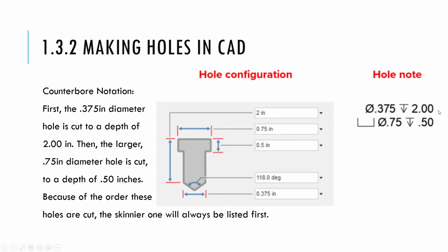You'll notice there's no units over here on the right side. That's because if you were to actually make this whole drawing in the industry, you'd say, okay, all the measurements on this paper are in inches, so you don't have to write inches after every single one. If this had gone all the way through, instead of this symbol and this number, you just write THRU, all caps. If you're annoyed by that, I am as well. It's just the way it is. It's something that I learned when I was first going through all this too.